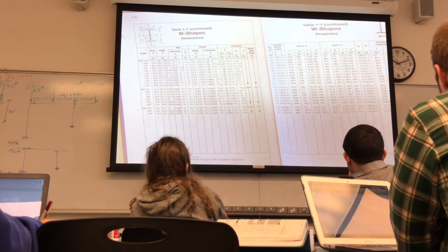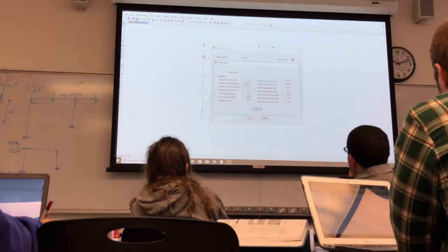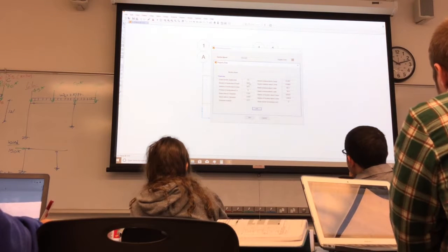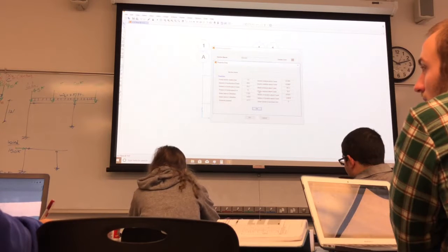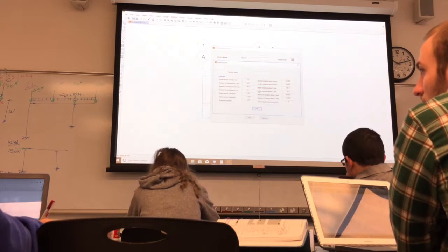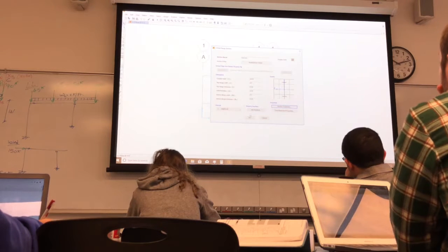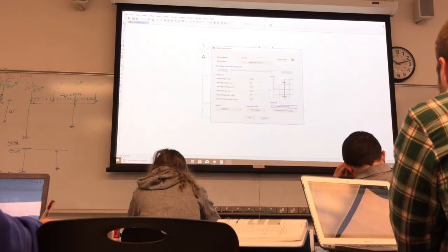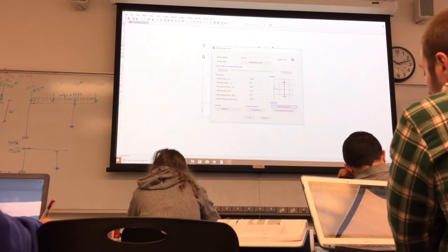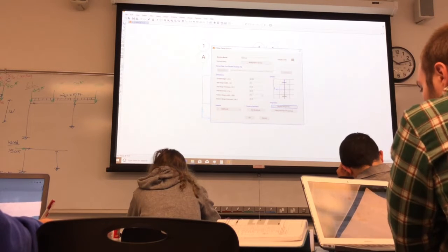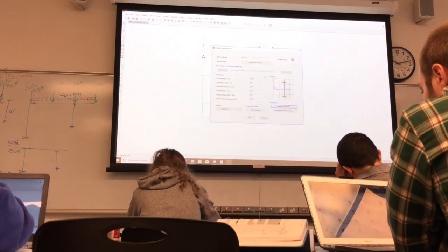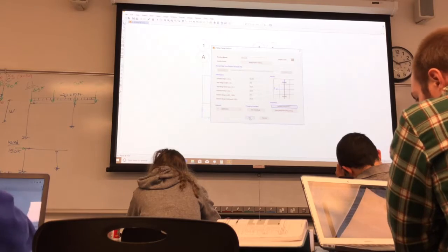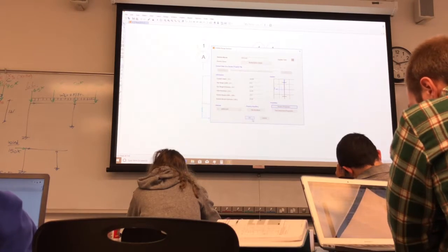So the moment of inertia is the same, 843. All these numbers you can compare. Same thing, you do it for a 14 by 99 or 14 by 109, you get the same answer. But that's in inches. That's why I changed the units into inches when I look at inertias and areas, because in square feet it's going to be completely different numbers, because the AISC gives it in inches.